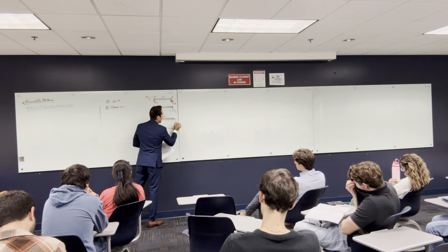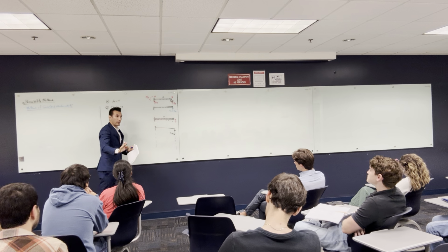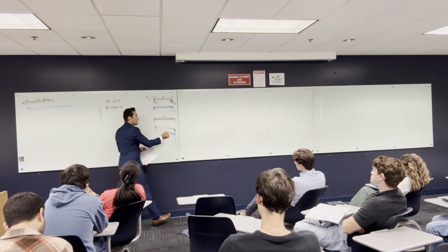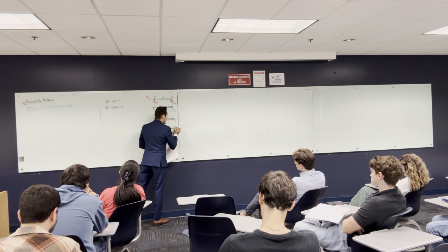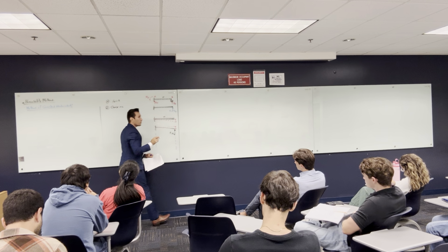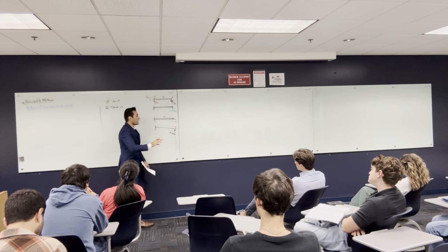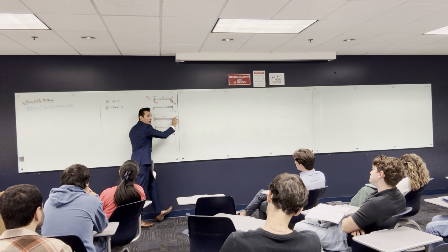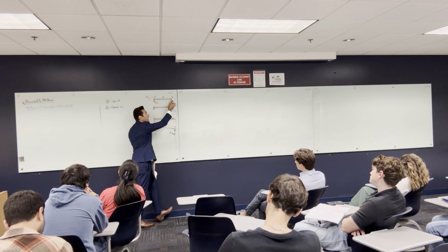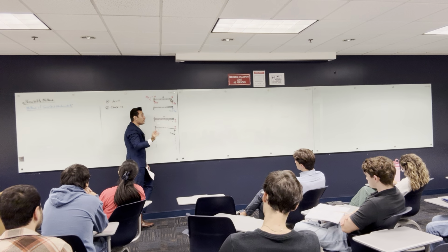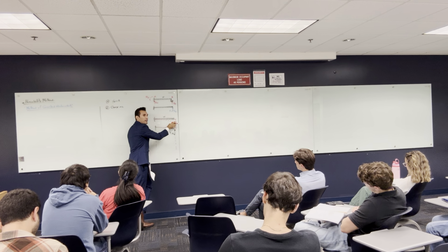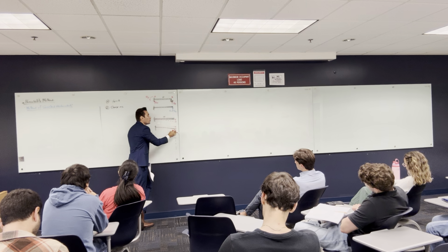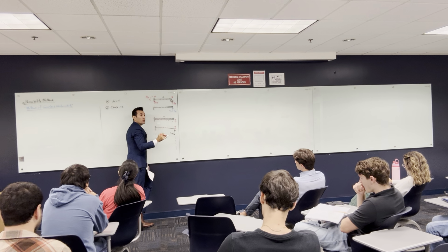And here you are going to have delta, right? The thing is, this one is going to make a deformation like this, and it's going to have another delta. So the compatibility comes here. The delta here is supposed to be equal to the delta here. Why? Because at the end of the day, you have a hinge here. So you need to find the value of the force F that is going to counter the delta that comes from this load to make the total delta equal to 0.